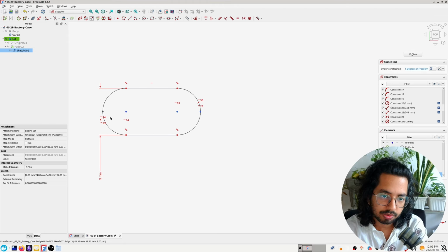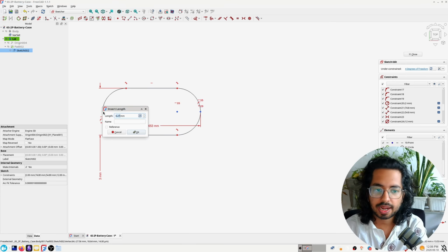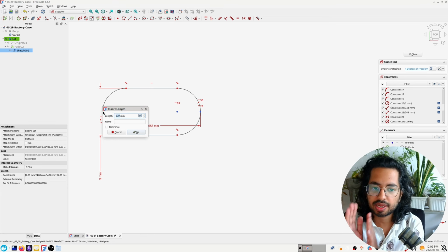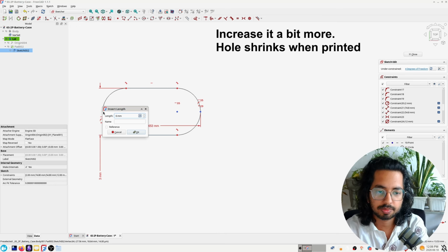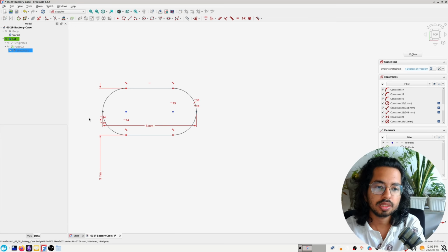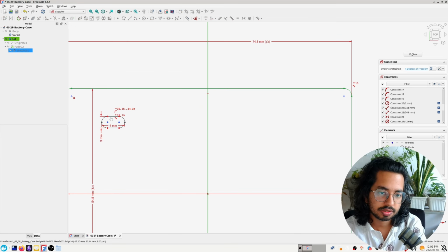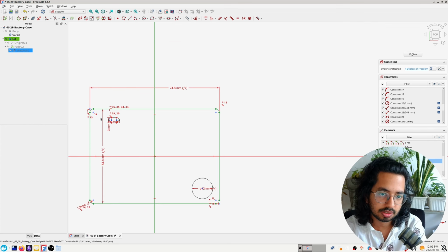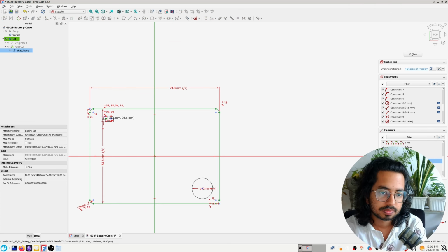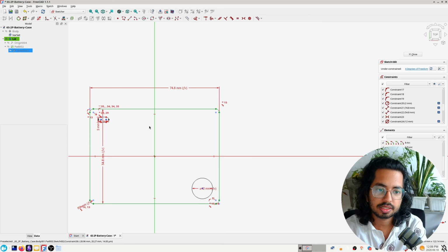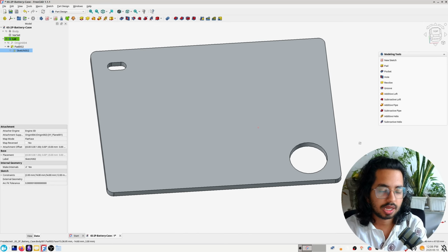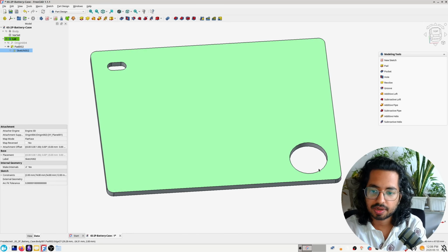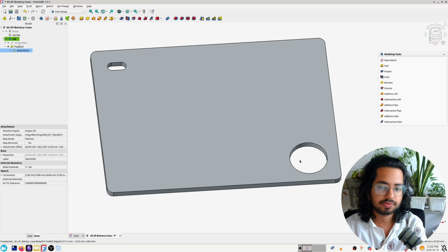So we take the outermost dot from both sides and press KD. Okay, and we know how much both our wires were. It was 6 mm combined. So there we go. This slot is done, but we can still move this. So I'll keep this in the corner right now. Later I'll show you how to fix this. Okay, click on close. There we go. This is the hole we have for the wire, and this is the hole we have for the DC jack.